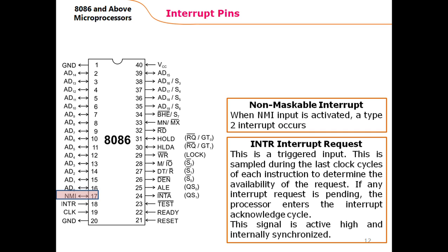When interrupt vector 2 is accessed, the 2 bytes of the instruction pointer are updated, and the 2 bytes of the code segment are also updated, and the interrupt service procedure defined for the non-maskable interrupt is accessed and executed, and the microprocessor then responds accordingly.